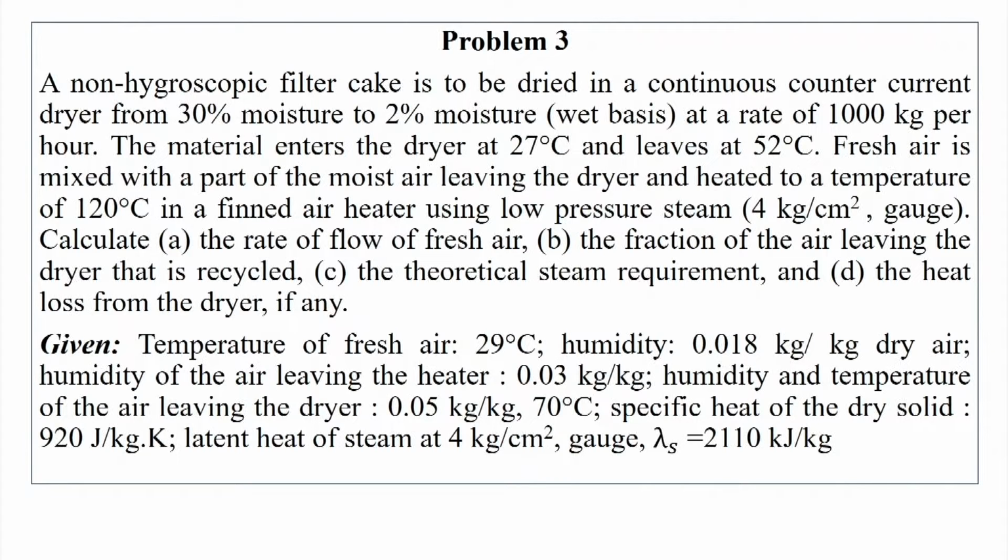Now we need to calculate the rate of flow of fresh air required to dry this wet solid, the fraction of the air leaving the dryer that is recycled, the theoretical steam requirement, and the heat loss from the dryer if there is any.